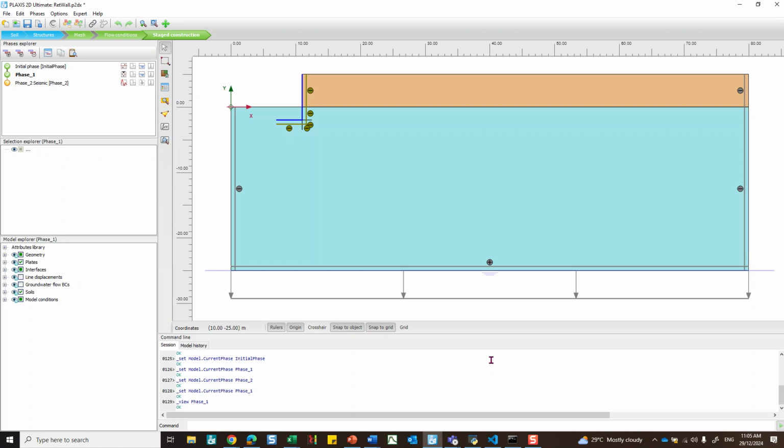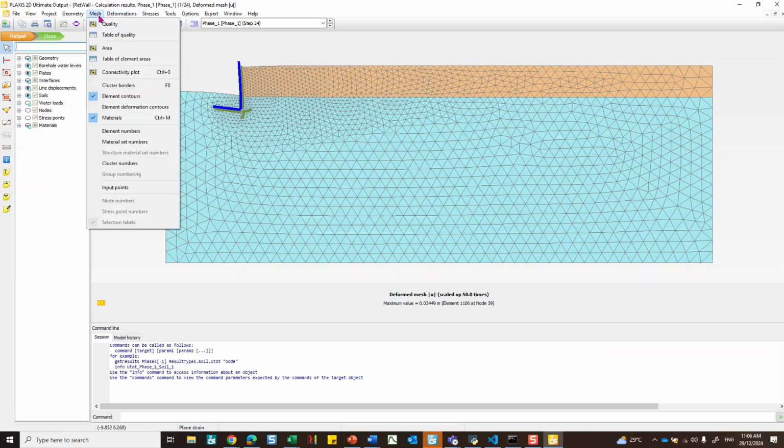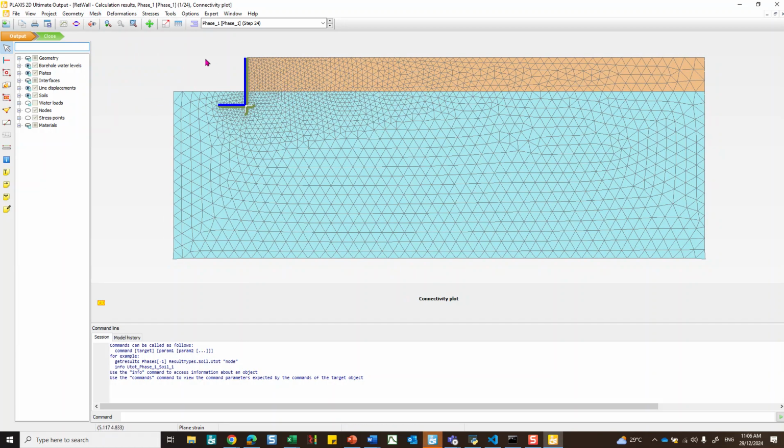This would help if, imagine, you have several dozens of instances of this retaining wall where the height keeps changing because of sloping ground or whatever, and you need to automate this process so that you don't have to go every time and see the calculation results, then double click on it, see the value and then go to the PLAXIS table. It's quite a slow and daunting task.